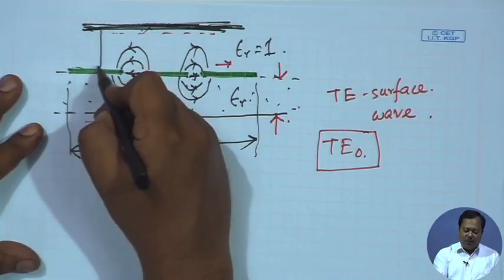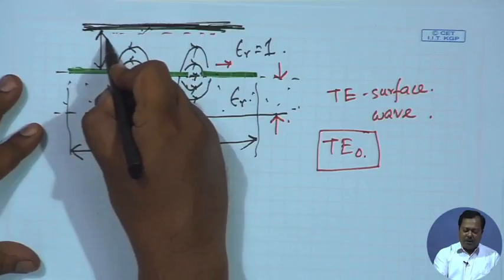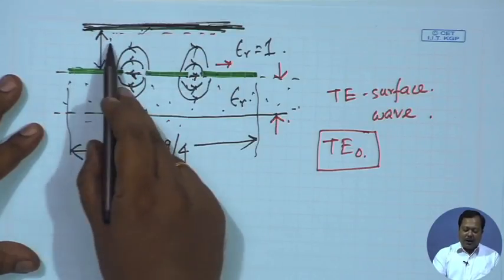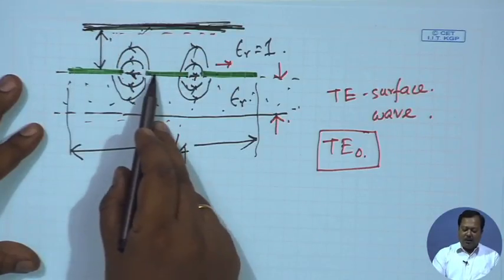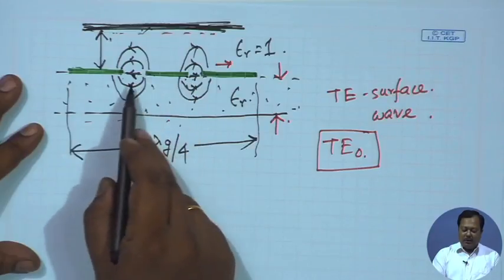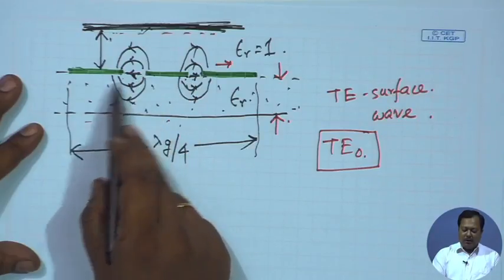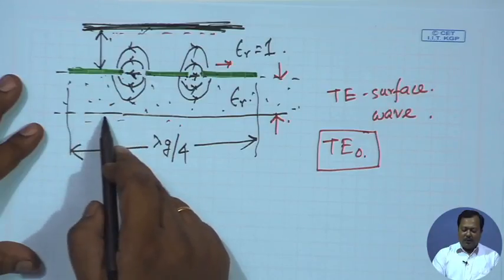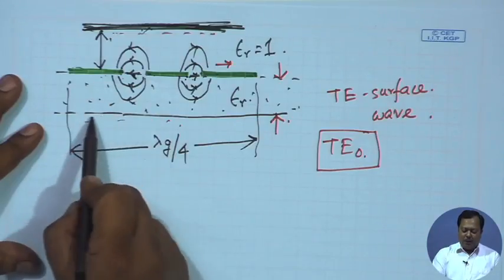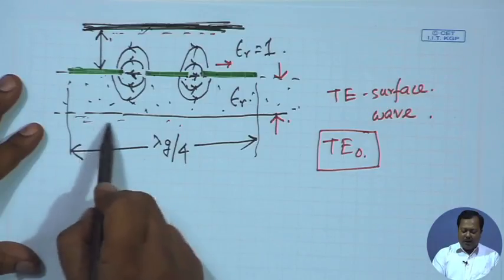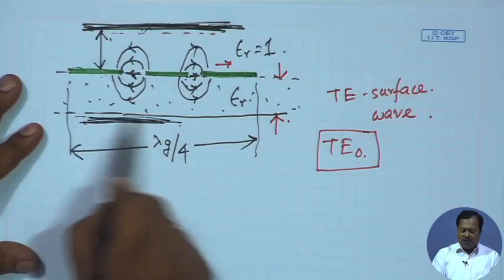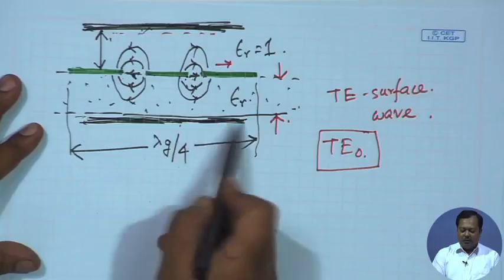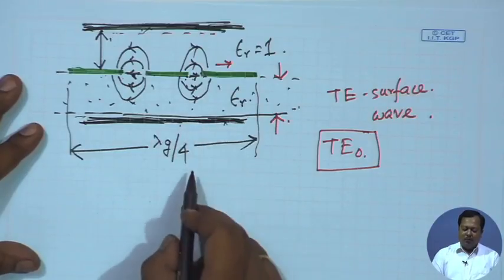So, we have to maintain a minimum separation for that, and that separation depends on the signal line width, the slot width, as well as the dielectric constant and the thickness of the substrate. Similarly, at the bottom side we can't place the packaging wall just attached to the substrate. So, we have a problem due to packaging.